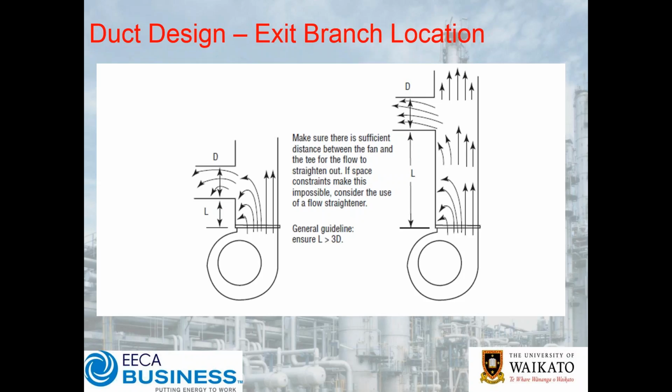And so what we're talking about here is we've got the air coming out of the fan, and of course we can have the offtake. Now the problem is if the offtake is too close to the fan, then that can cause all sorts of problems. Now the other thing of course is that we haven't shown on this picture, but I'll highlight it at this point. If the air is rotating like so, the last thing we want to do is to have our offtake over here.